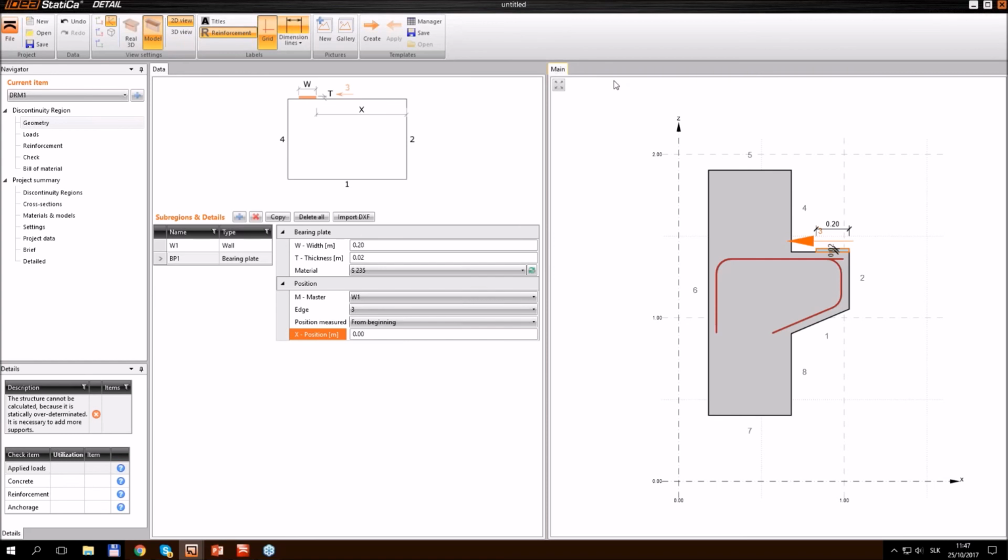Although we use a few things from the 3D positions, we use a 2D finite element model. Like I showed in the detailed example, it's represented by its midplane. But as for the embedment, we calculate it from the position of the rebar in a cross section. It means we also calculate the influence of the near edge for each rebar, right? But in the end, it's based on the overall area of reinforcement in a longitudinal section.